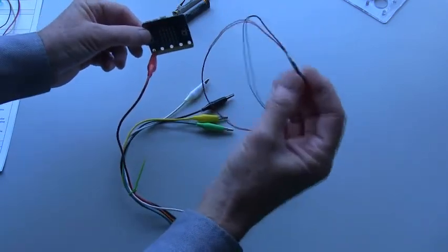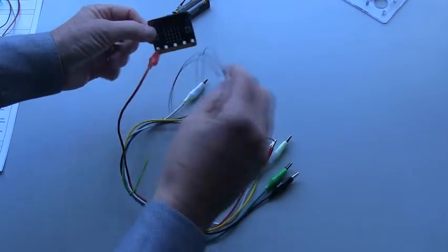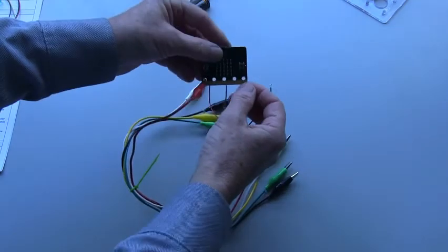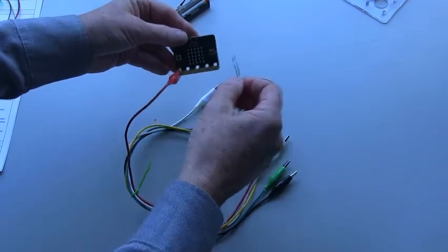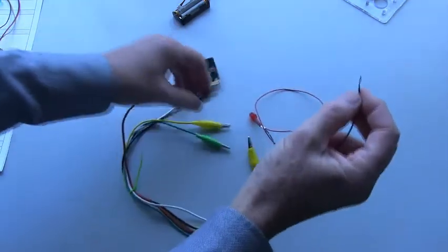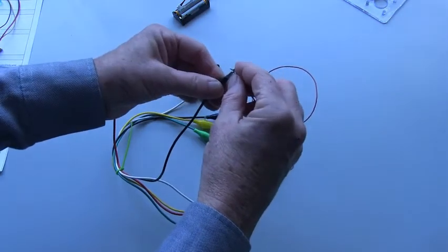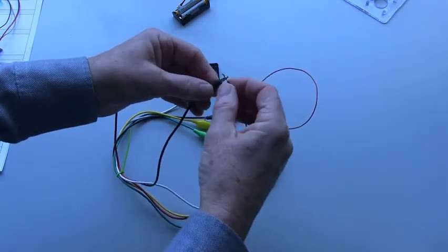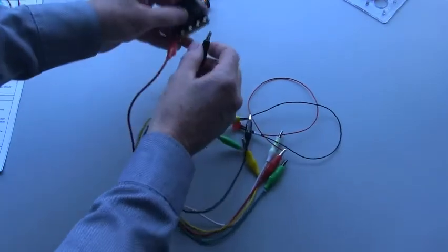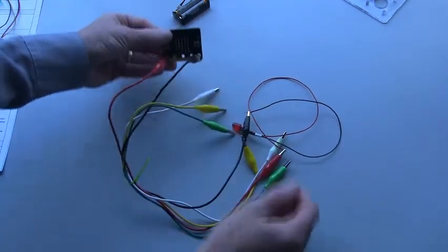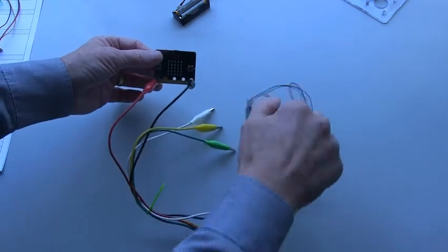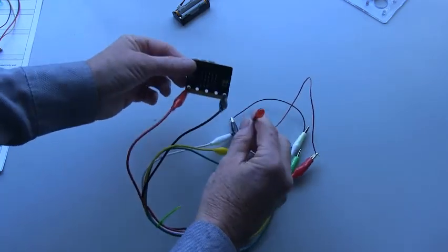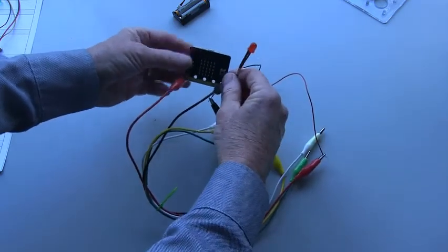So I've put my red wire to pin 0 and the black wire has to go to the GND pin, the ground, the earth pin if you like, the negative side. So I'm going to use my black crocodile clip for that and connect it to the ground pin. Okay, so now my red LED is connected to the microbit, and as I previously downloaded the code, if I